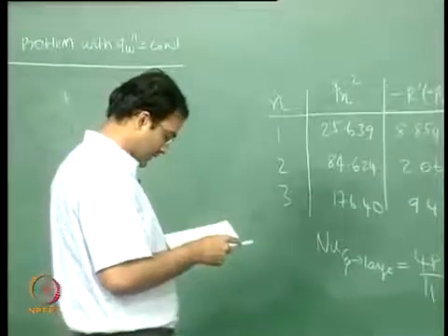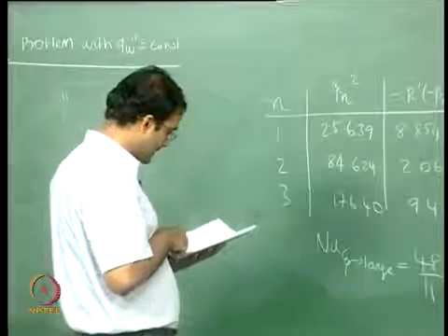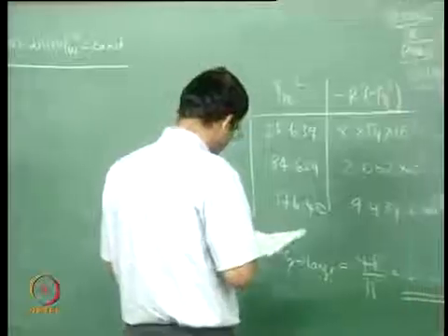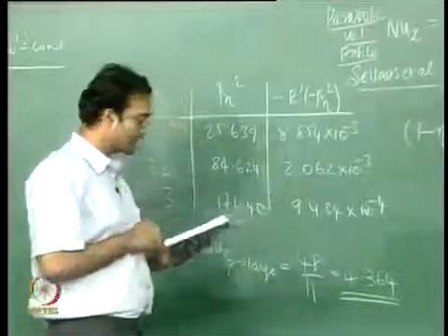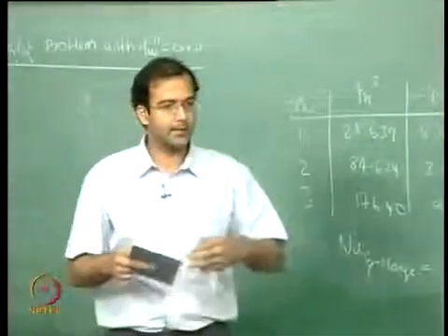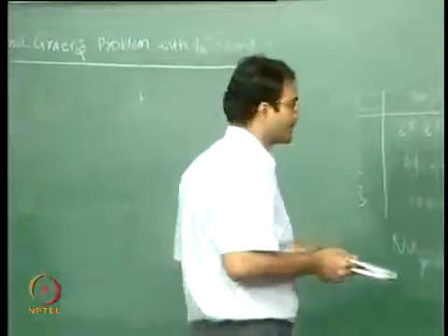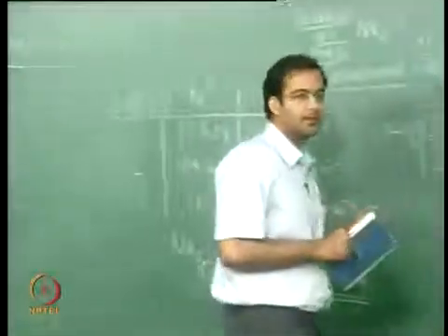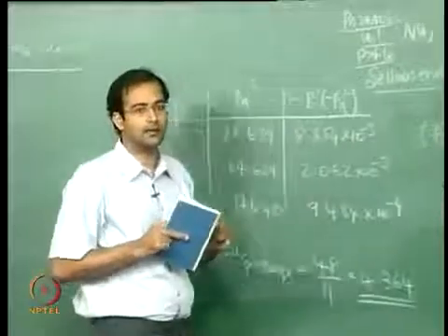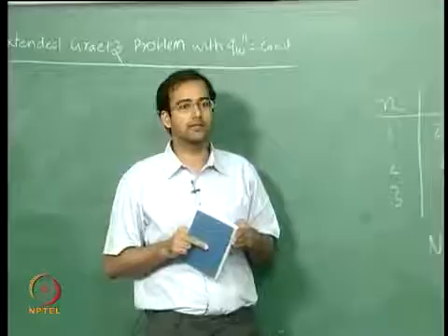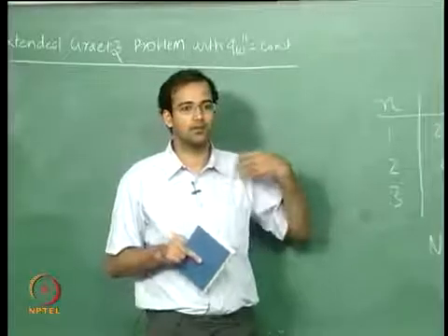Of course Sellars also did a case where he did a linear wall temperature variation. So he did all the three. He looked at the parabolic velocity profile, and he looked at constant wall flux condition and also linear variation in the wall temperature, and he has also given the solution.